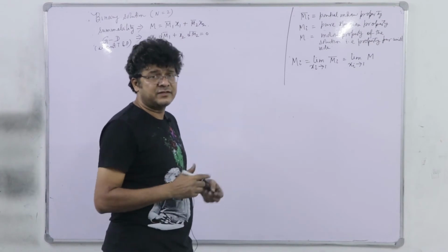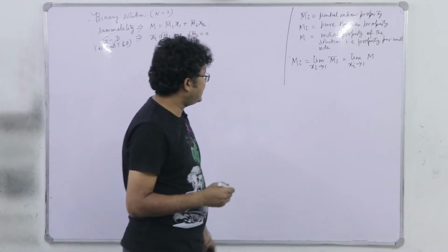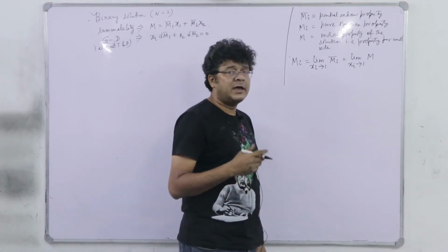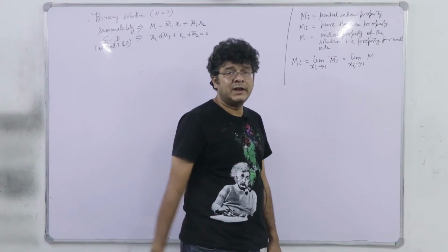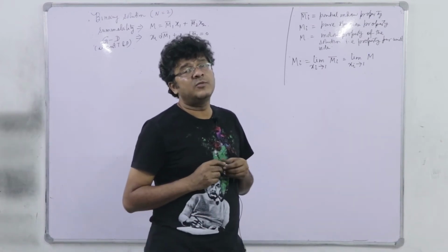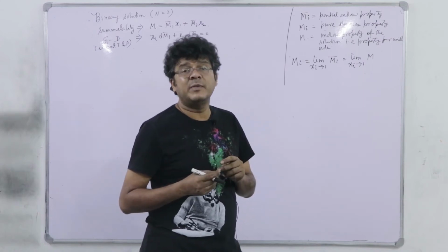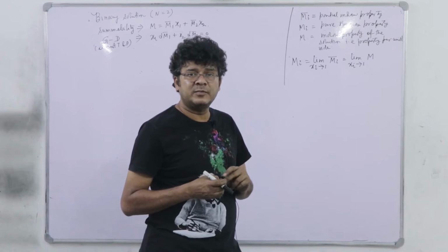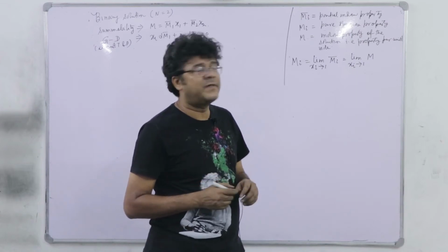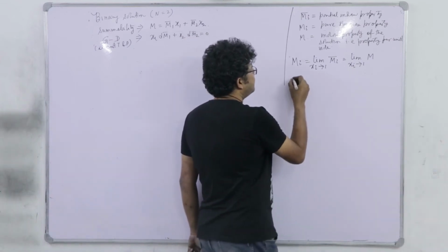Now, the other extreme, if I set xi tending to 0, what will happen? Here the partial molar property will not vanish, but even it may increase than the pure species property, and that is called infinite dilution property, right.